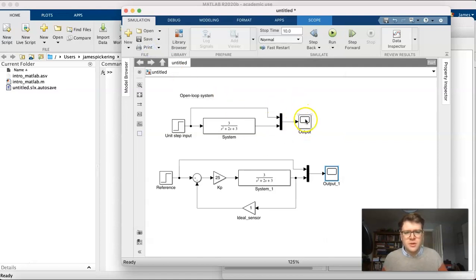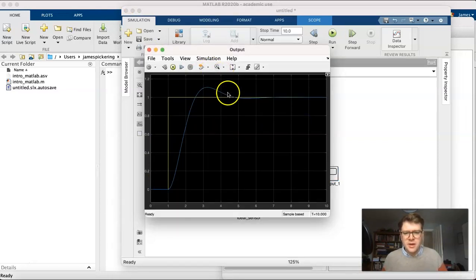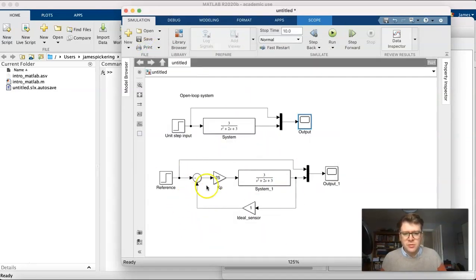So what you've noticed when you're running this is that you're getting just the open loop system. It's not so common to talk about steady state error there, but you can see 1 in, 1 out. Here now, in terms of proportional control gain system, you're getting a difference, so a steady state error between the two signals, the reference and the output. And as you increase proportional gain, it reduces, but you introduce more oscillations on the system response.